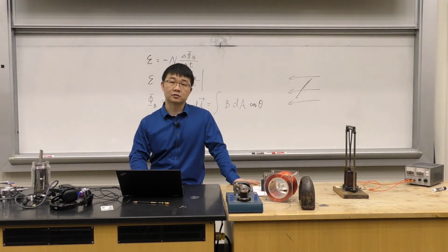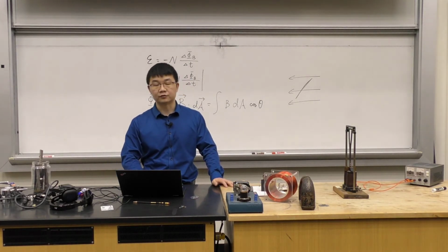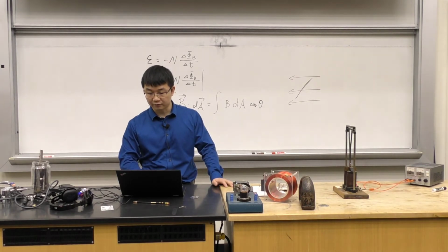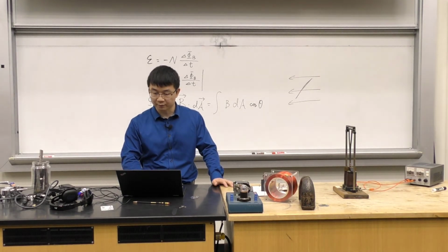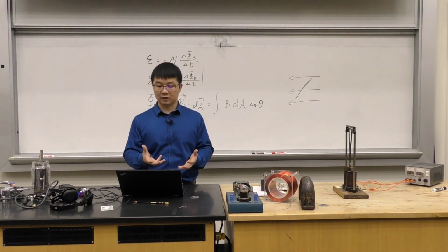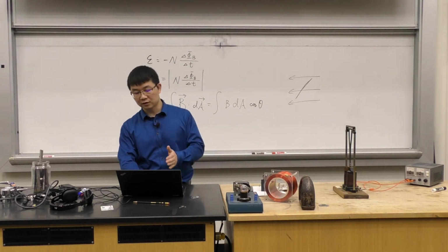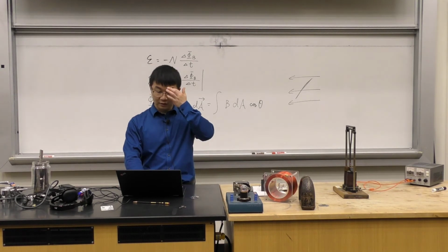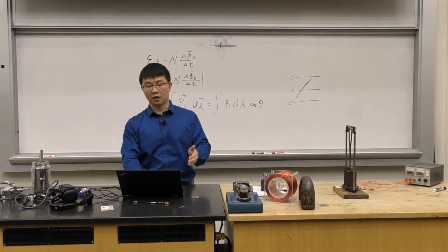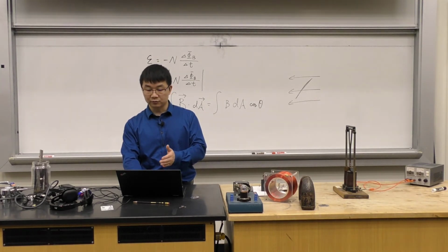And they're eddy currents. Now these eddy currents are going to have their own magnetic field, B prime. This B prime is also a changing magnetic field because everything is changing here. The B prime goes through the receiver coil on the right, and then it's going to induce I prime, the loop current on the receiver coil.